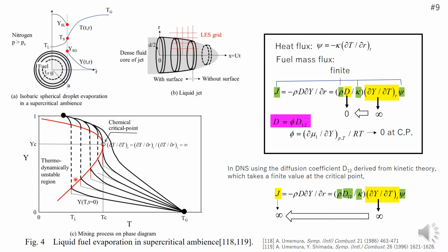The y value jumps at the droplet surface. As the surface temperature rises, the gap is reduced and vanishes when the surface reaches the critical state. In this case, the y-curve must take the form illustrated in this figure, indicating that dy/dT should diverge at the critical point so that the subcritical evaporation regime might change to the supercritical evaporation regime continuously.